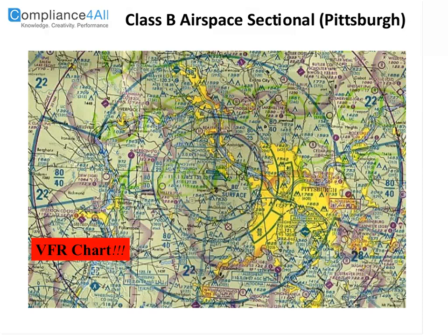If you don't want to talk to ATC, another thing about the ATC system is they try to design airspace to minimally impede all the users. So if you're a VFR operator and you don't want to talk to ATC, but you're going up here, for example, you can take off from Washington County Airport up here, and you can see the airspace. The airspace here is 48. That's what the IFR airplanes are operating in. So if you stay below these altitudes, you can go right along here, underneath, right near the airport, and just stay out of the way, and you can go fairly directly to wherever you're going just by staying beneath. You can go almost over the city of Pittsburgh and not be in the way.